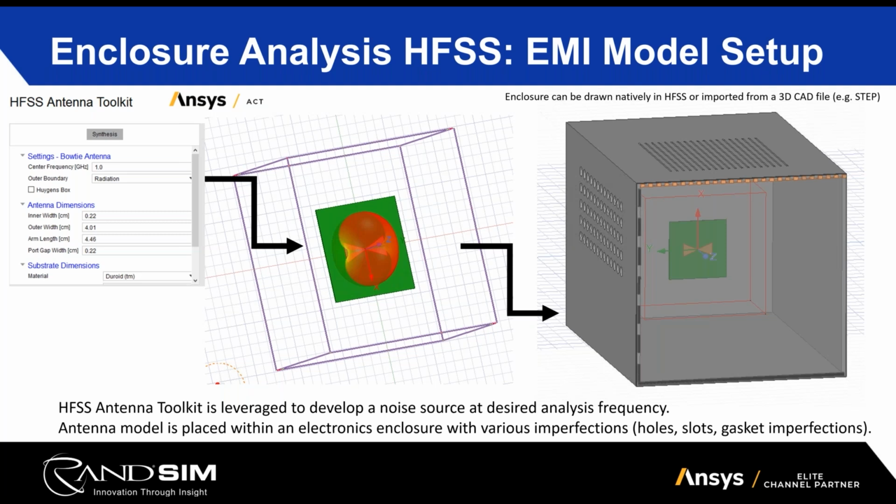A perfect metal enclosure usually will do a great job, but it's going to have gasketing, it's going to have slots, and especially as we go higher and higher in frequency, the smaller and smaller the wavelength will be, which means that smaller and smaller structures will be able to let EMI come out. An enclosure that you used 10 years ago for lower frequency shielding may not work as well if you're moving into a higher frequency space of today and tomorrow.